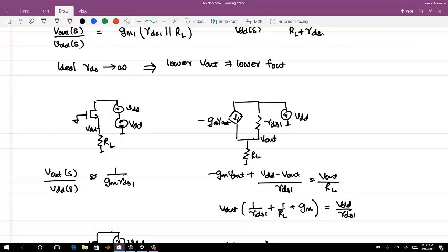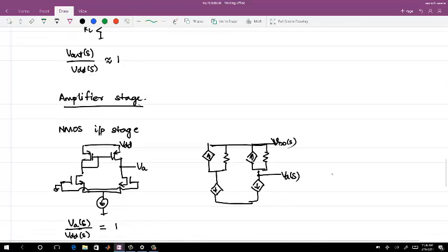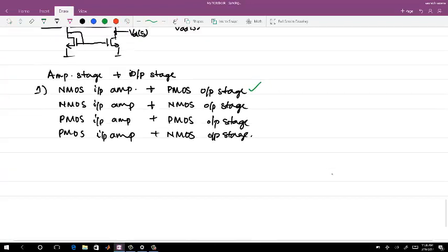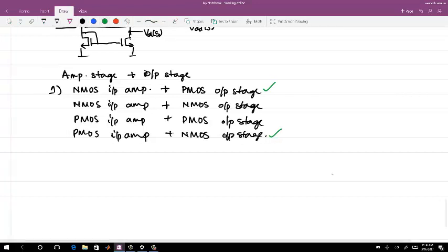So the better options to consider are these two when you are considering the supply noise regulation, for these two kinds of amplifiers and output stages. I'm not talking of any complicated other method. So don't take it always as a general one where you may be using a folded cascode or some amplifier and say, because an input pair is always better, I will use the input pair.